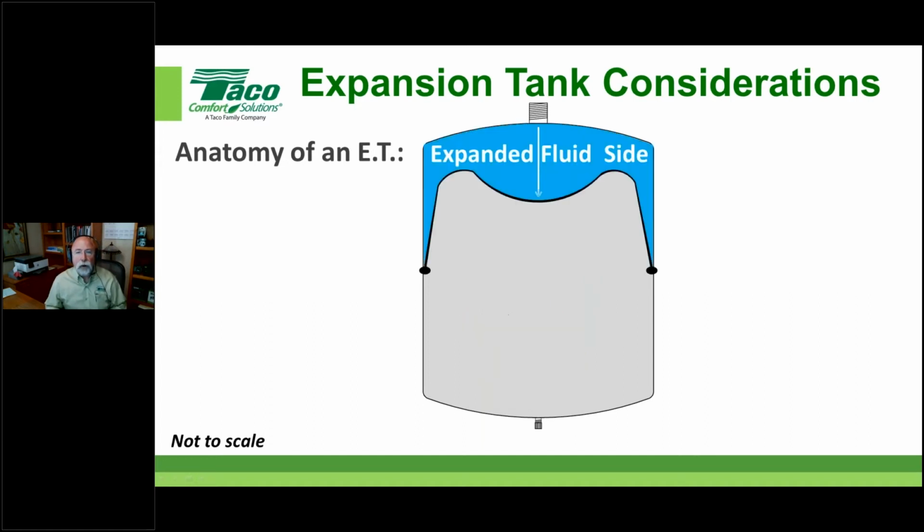Now, if we start actually filling the system up, as the fluid expands when it's heated, of course that's what happens to this EPDM diaphragm. It starts pushing back out there. That EPDM diaphragm moves as the fluid moves.